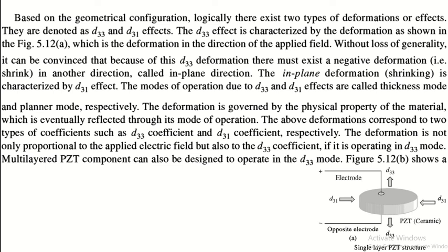The thickness is governed by the physical property of the material, which is eventually reflected through its mode of operation. The above deformations correspond to two types of coefficients, such as the D33 coefficient and the D31 coefficient respectively. The deformation is not only proportional to the applied electric field but also to the D33 coefficient, if it is operating in D33 mode. A multi-layered PZT component can also be designed to operate in the D33 mode.